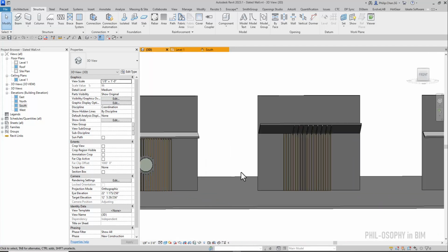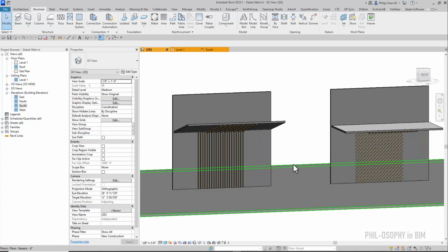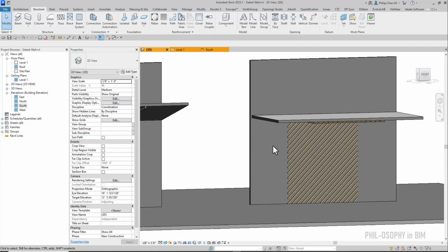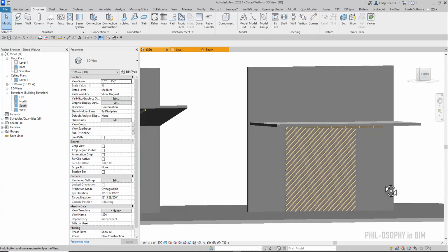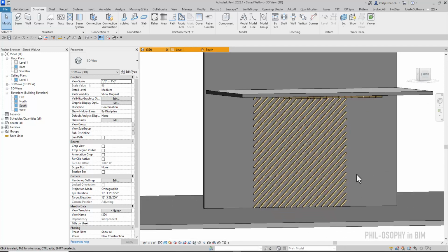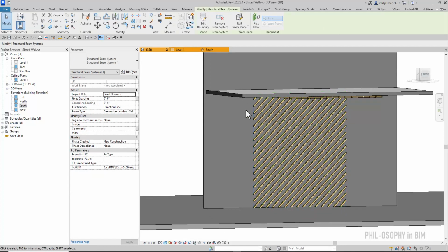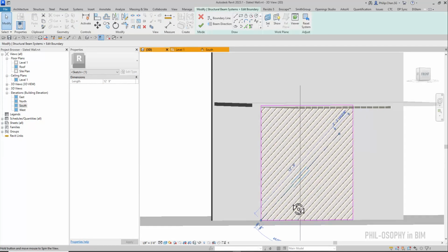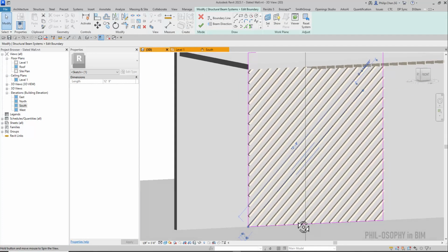Okay, so one last thing here. Because of the direction line, you can use that by doing something like this. You can see that now I have a slat ceiling that is going in the diagonal direction. The way that I do that is by just using the direction line. So let's take a look. You can see that I have a direction line going 45 degrees here.